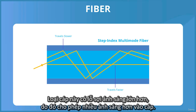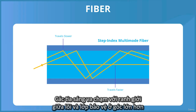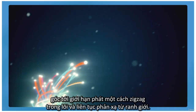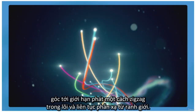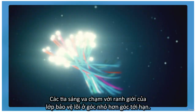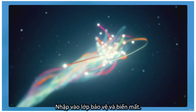This type of fiber has a larger light fiber opening, thus allowing more light to enter the cable. Light rays striking the boundary between the core and the protective envelope at an angle greater than the critical angle propagate in a zigzag pattern in the core and are constantly reflected from the boundary. Light rays striking the core protective envelope boundary at an angle less than the critical angle enter the protective envelope